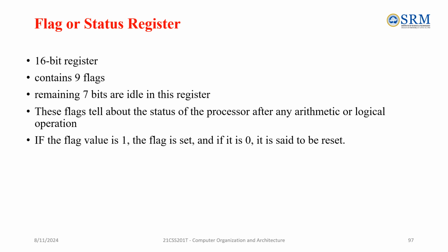So the flag or status register is a 16-bit register that contains 9 flags. The remaining 7 bits are idle. These flags tell the status of arithmetic and logical operations. If the flag value is 1, the flag is set, and 0 if it is reset.